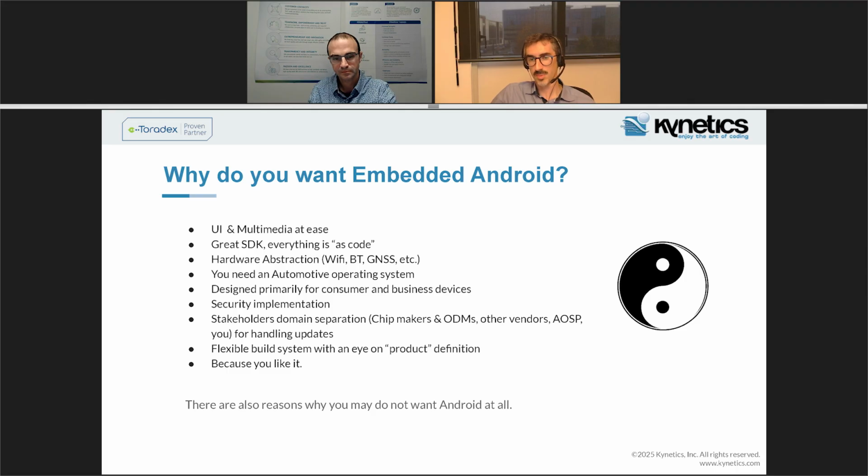So you can end up using one previous version of the drivers and the libraries to support a specific SoC, provided, for example, by NXP or by Texas Instruments, but also update to a newer version of user space. So, for example, using the latest and greatest Android mechanism, like the use of GSI, which is actually to be able to use the latest version of Android, even with old drivers, let's say.